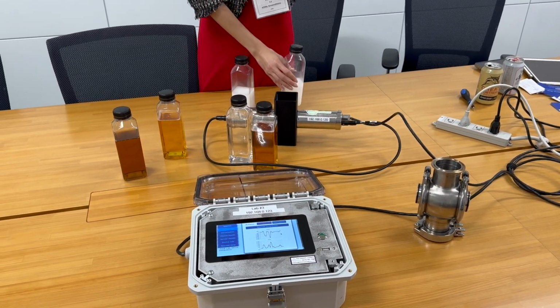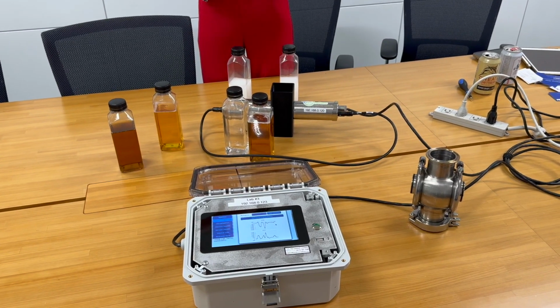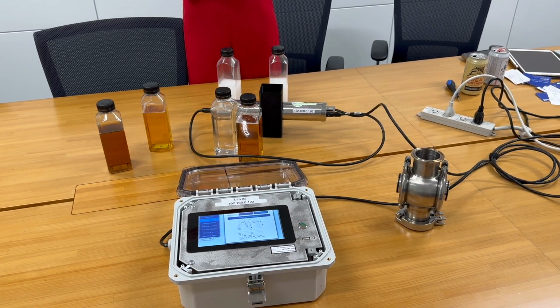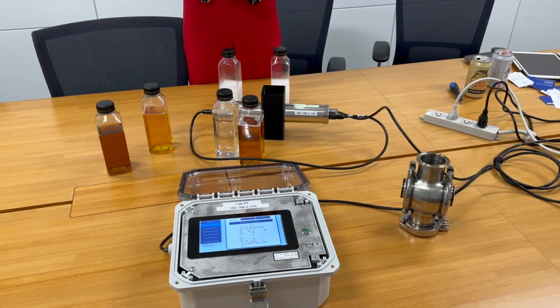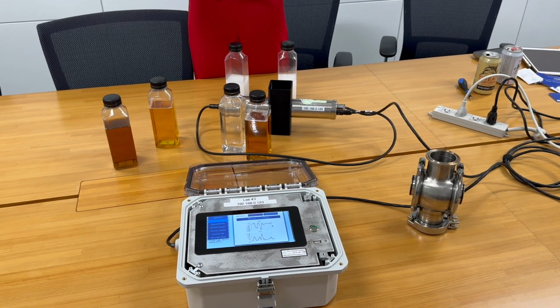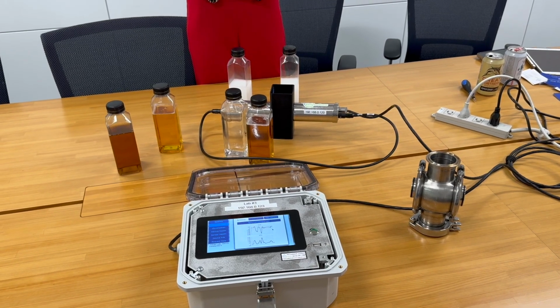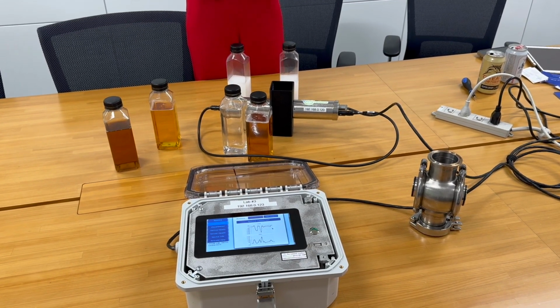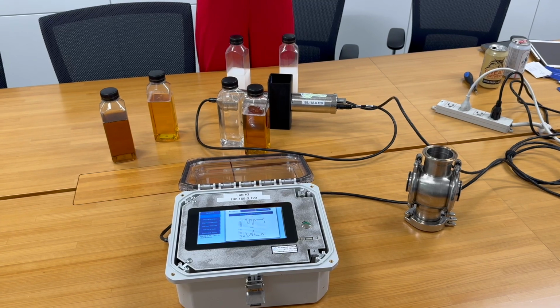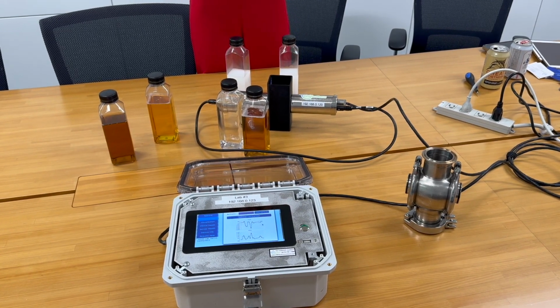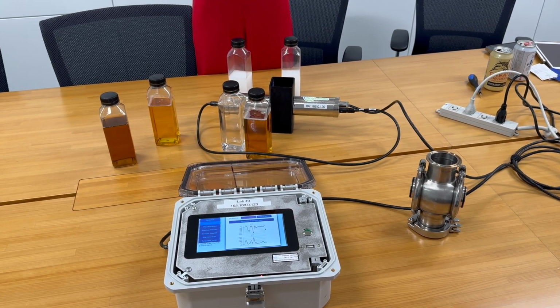So you're pushing this common material, and then you start dosing this new fragrance, and all of this product goes to waste. So the common base that's in between, and also the timer that's set on the new fragrance that we're dosing, that also is sent to waste until it finishes that time, and then we send that to the filler to allow for stabilization traditionally.